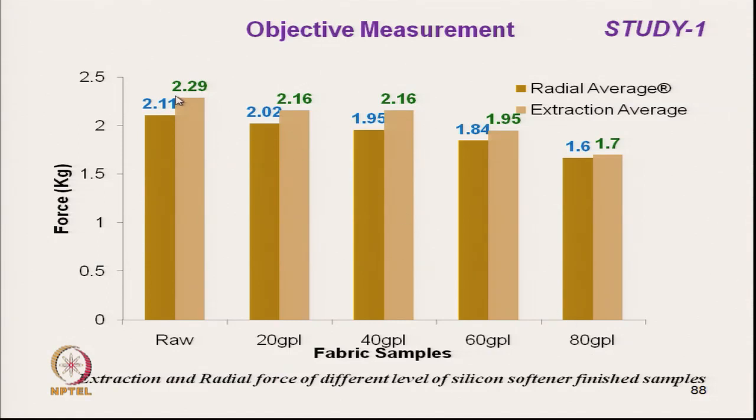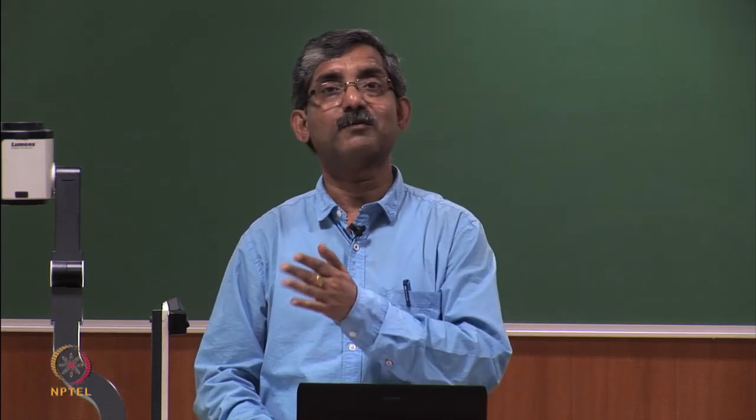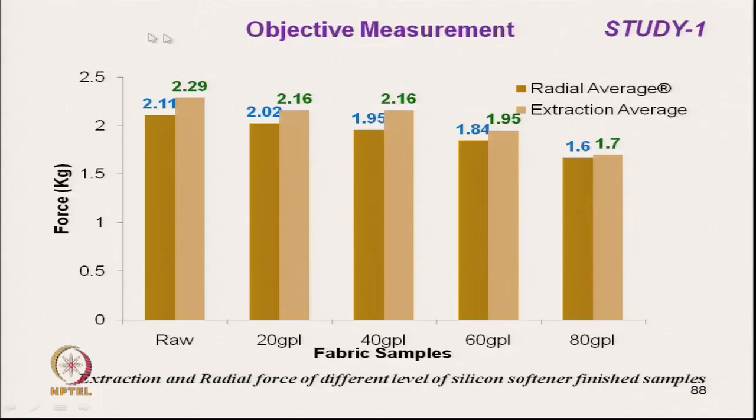With the increase in finishing level, we observed that the extraction force reduces. That means the fabric becomes softer, or the force required to extract the fabric becomes lower as the fabric surface becomes smoother. This gives an idea that objectively we can test the fabric fill.